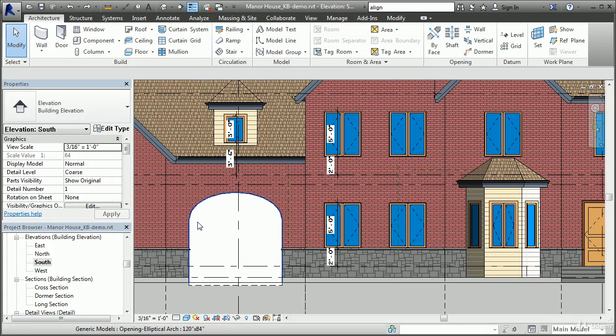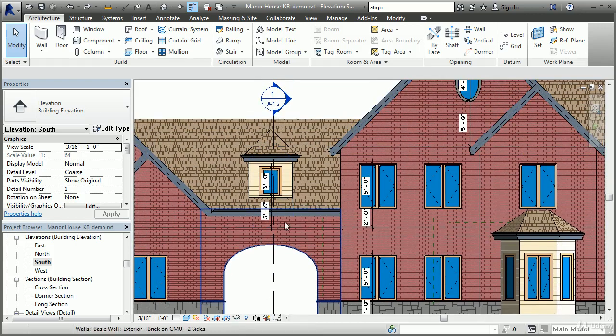Other benefits to working within a BIM approach include a better understanding of the building and its spaces by being able to easily view the model in 3D. Fewer errors in cross-referencing views and details, interference checking for conflicts among various structural, mechanical, and architectural elements, automated schedules and quantity takeoffs. If we'd like to see what this building is going to look like through this dormer section,